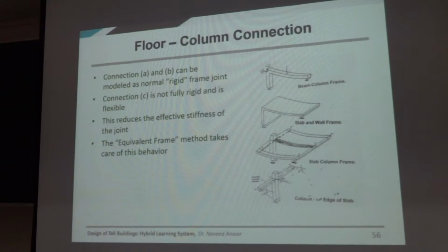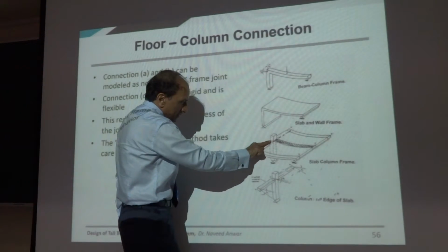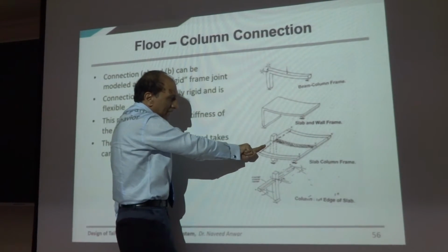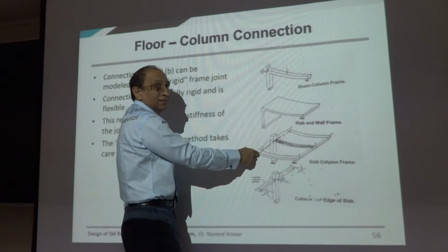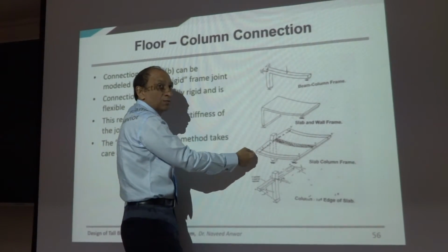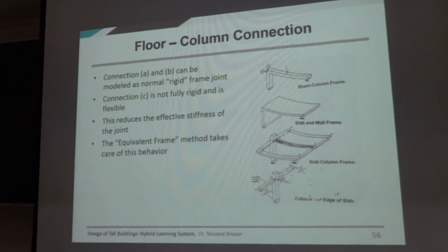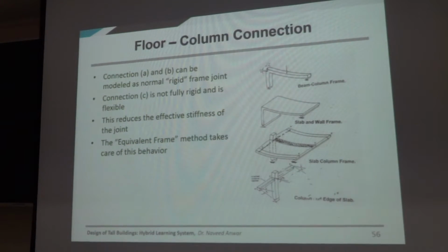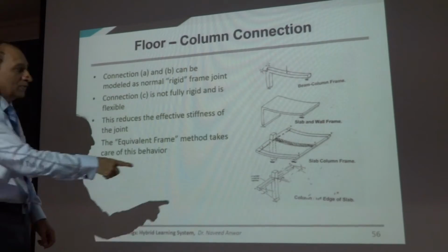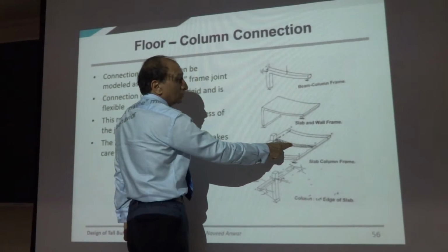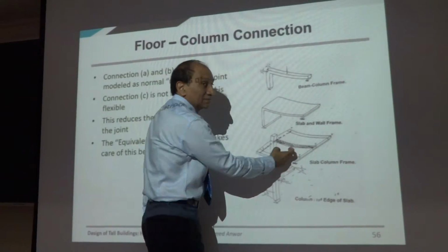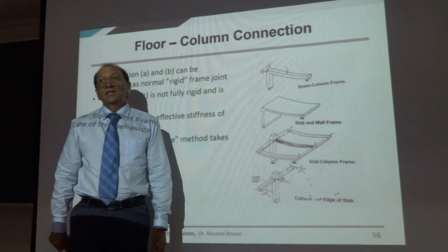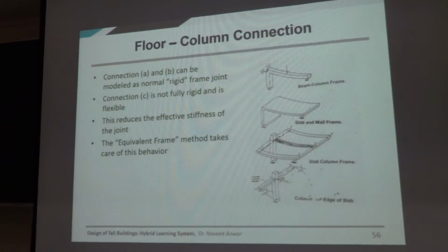And that leakage is happening because of two factors. One is the twisting of this beam, because if this was completely rigid, then the deformation here would be transferred here and would transfer to the column. But this is not rigid. This is twisting and it's also deflecting. So we have two contributions to the reduced stiffness: the transverse deflection of the strip, and also the rotation of the strip, which is causing the middle displacement to be more than it should be, more than here. So the average displacement will be different from what you get here. It will be more.